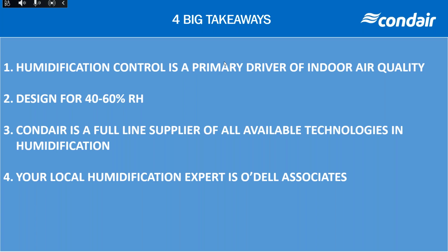Okay. Yeah, so I would say yes. The answer to that would be yes. You do want to ensure when you're placing supply and return grills that you're generating air currents within the space, especially in a hospital environment, keeping the cleaner supply air at the face of a patient or up top of the bed, and keeping the return air further away from where people are breathing.